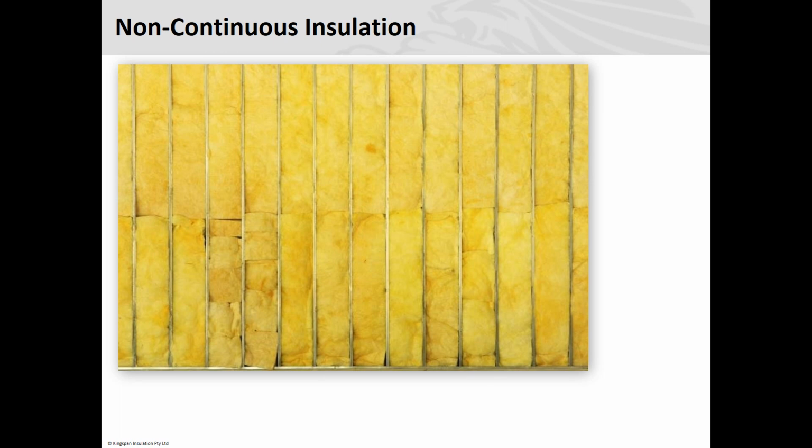And these mobile houses that are built in yards, what's the most common sort of insulation they use? They'd be using between their wall studs probably an R2.5 glass batt insulation. I would have thought so.